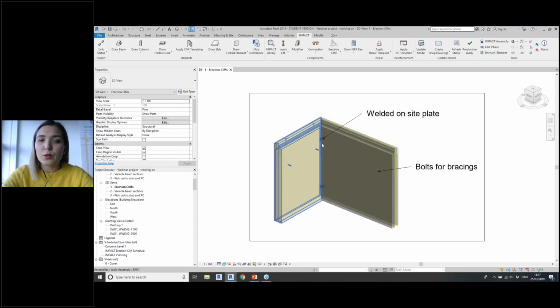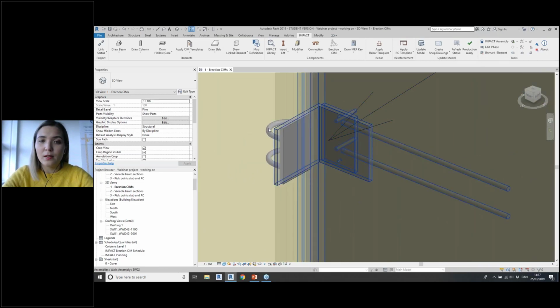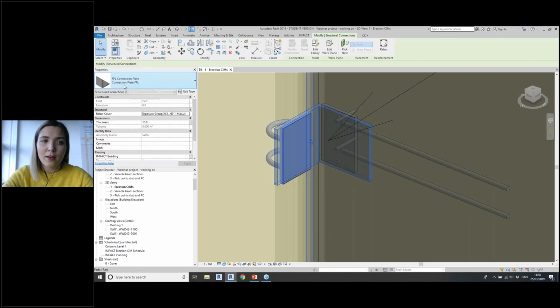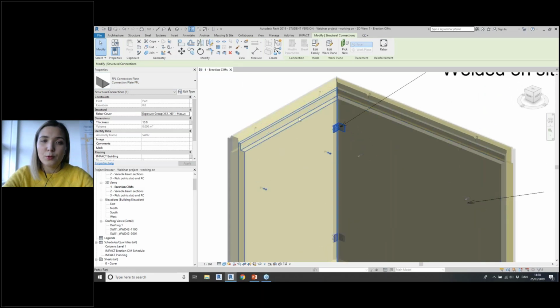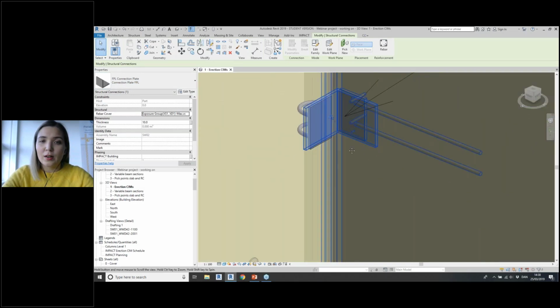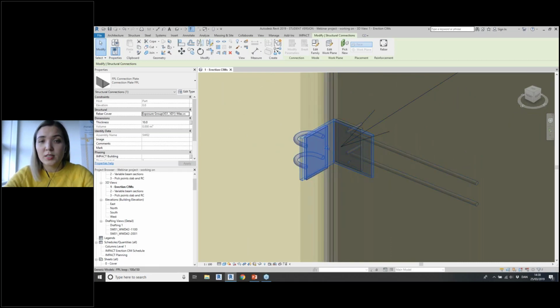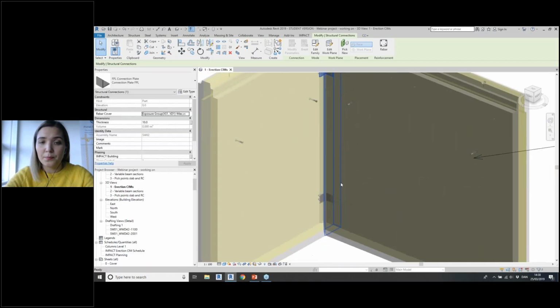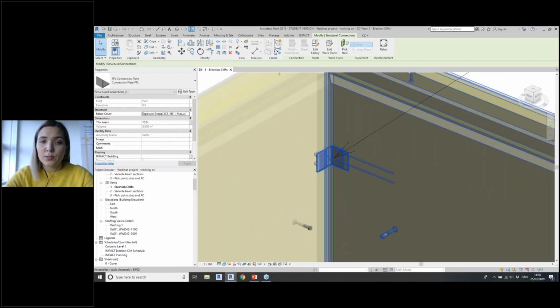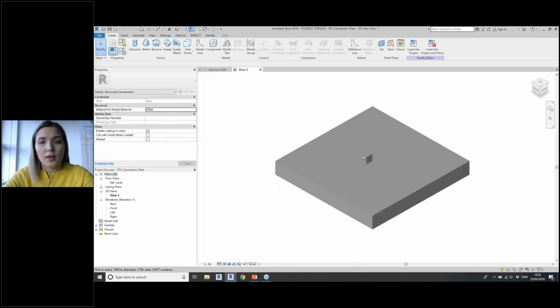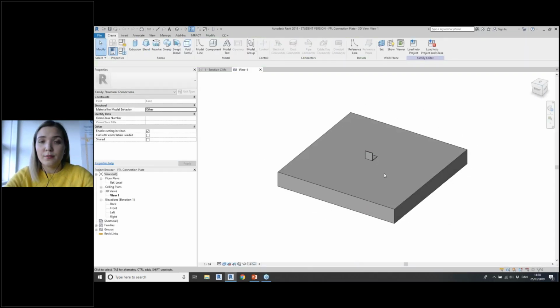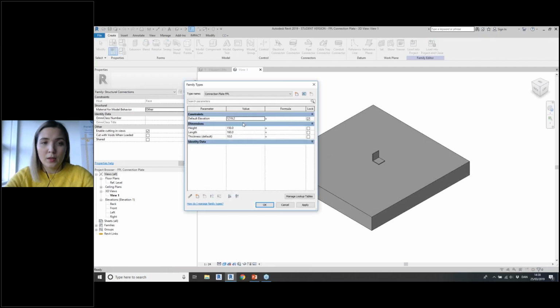So I have those two walls where I have made connections for FPL, anchor, and loop. I made a very simple family, FPL connection plate, which is face-based, and it was placed on the sandwich wall on the left side. To make this erection cast material, I will simply select one instance. I have two of them, but this is the same family. So I will go into this family. As you can see, this is a very simple face-based family with just a few parameters I made. These are the only 3 parameters that I made.